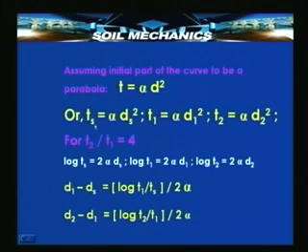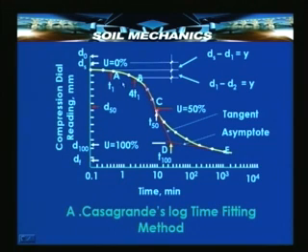This means that at the starting point, Ts must be equal to alpha ds square, at point A it should be T1 equal to alpha d1 square, and at T2 it should be alpha d2 square, and since T2 by T1 is 4, we find that on the logarithmic scale d1 minus ds and d2 minus d1 are both equal, absolutely similar, and that is the basis for computing this distance and arriving at the correct starting point ds.